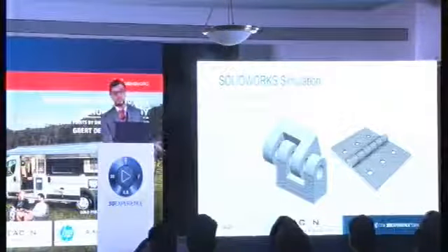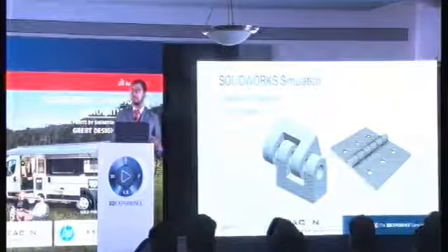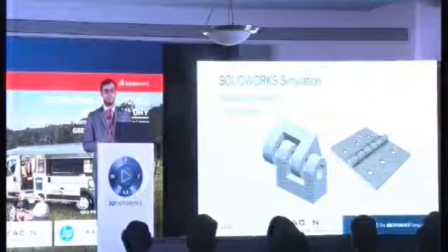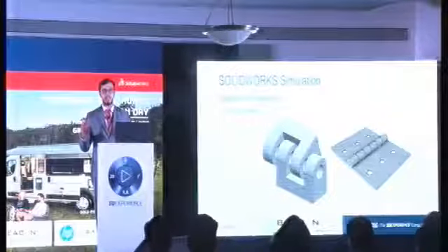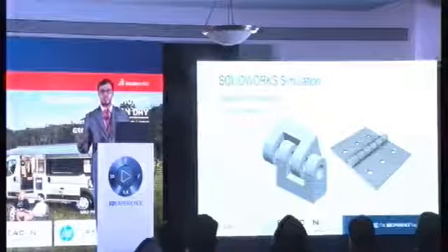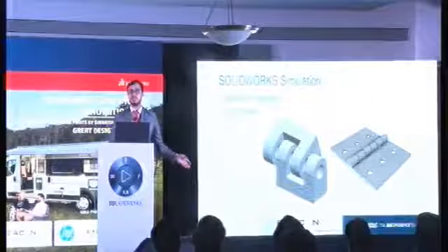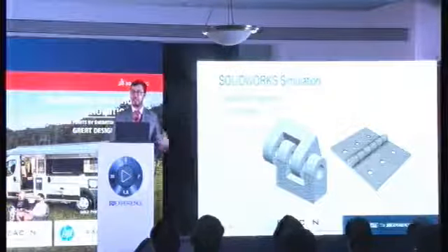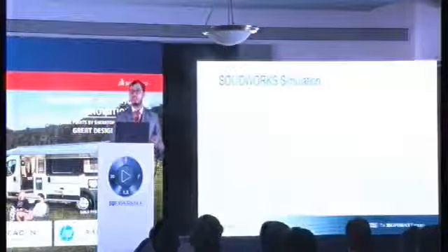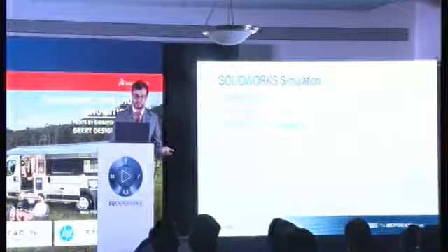Also, we have connectors. Connectors are a great way to define certain objects such as bolts, pins, springs, etc. So I can define up to 10 faces with the pin connector, enhanced pin connector as well. Previously it was just limited to the 2 faces.